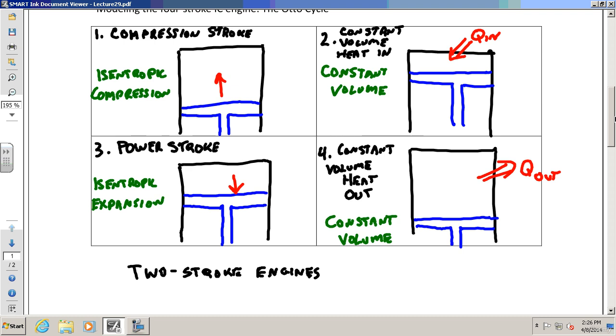Well, then why don't we have cars? If we get more power per weight, why don't we have cars that have two-stroke engines? Not necessarily lower efficiency, but the problem is that you tend not to have a complete combustion when you do a two-stroke, and the four-stroke process does a better job of completing the combustion process and ends up being cleaner. I don't know how much gas-powered lawn equipment you've run, but have you noticed they push out a lot of smoke? Can you imagine your car putting out that much smoke and junk? It's just not as clean a combustion.